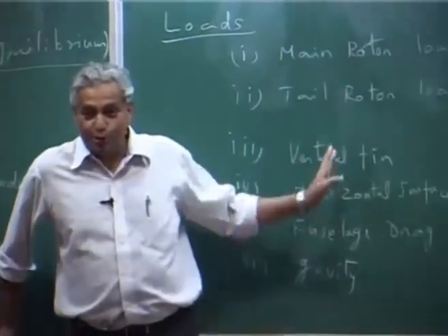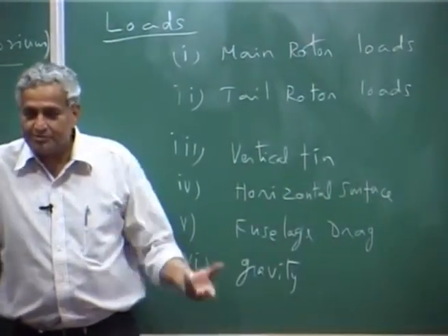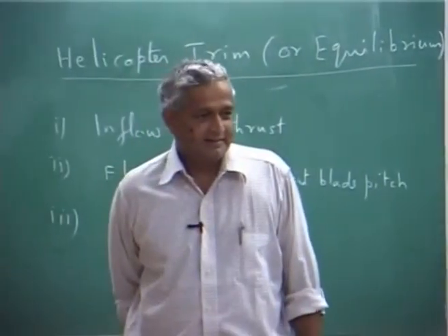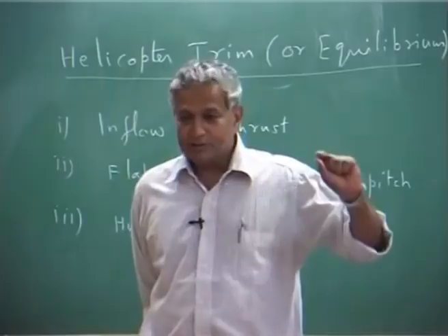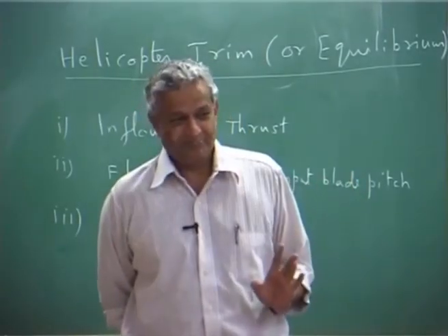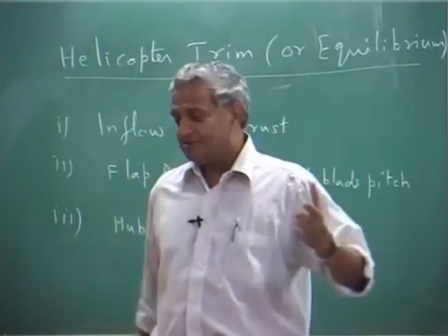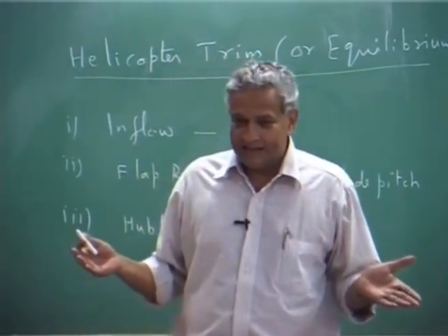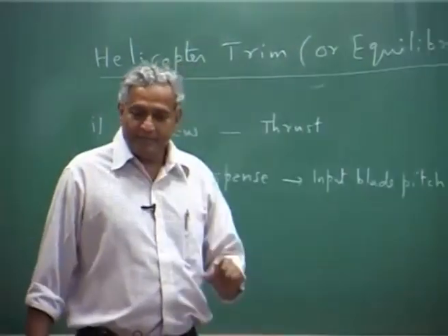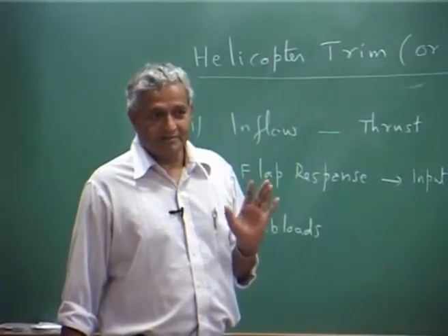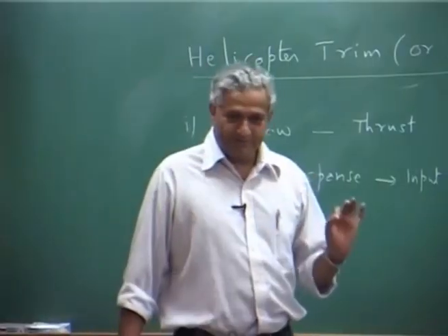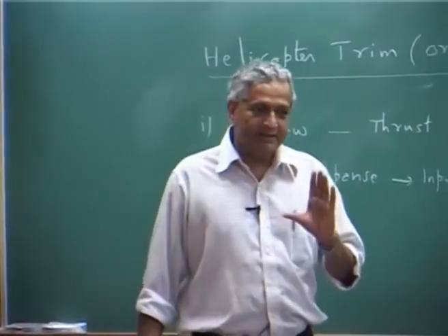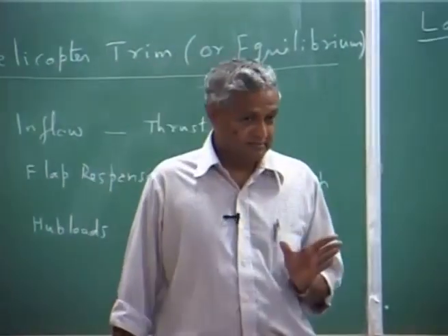Now, once you have the loads, you have to transfer all the loads to the center of mass, but that means you must know the location of the center of mass for a particular configuration, meaning the weight, how much fuel, how much everything. And then write the 6 equations of equilibrium, 3 force equations, 3 moment equations, but they will be in a particular coordinate system.